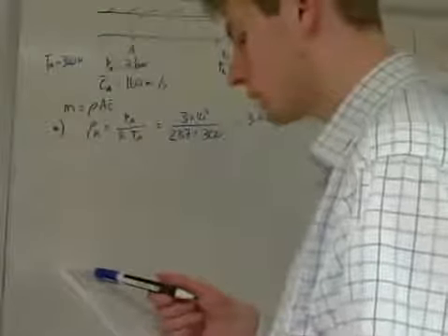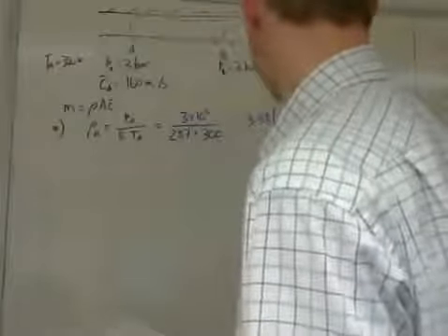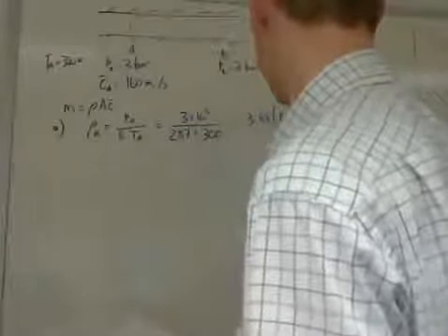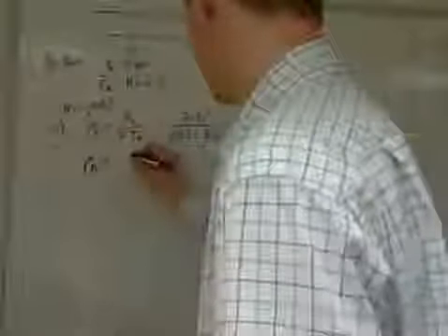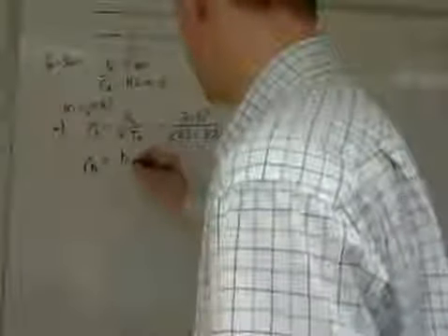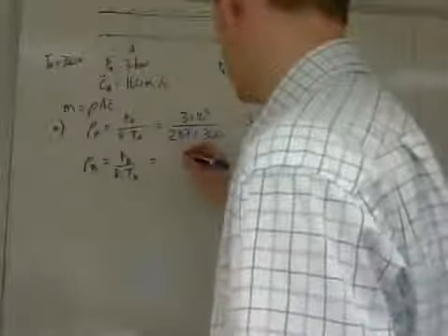In fact, we do know what the temperature at B is. We're told that it's an isothermal process. So TB is also equal to 300 Kelvin, or 27 Celsius. So given that, we can say that the density at point B is equal to PB over R TB. We know, in fact, both of these quantities.